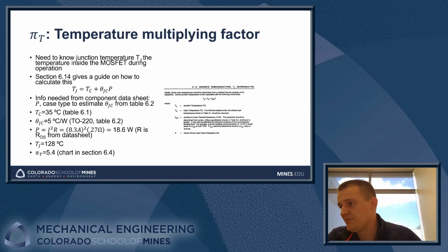We're above the absolute maximum rating of the transistor, which means our failure rate is going to be very, very high. So just a word of warning, if you come across something like this and you're exceeding the stated rated maximums of a component, our failure rate model is not set up to calculate that, and all bets are off, and you should just assume that failures are going to happen at that point.